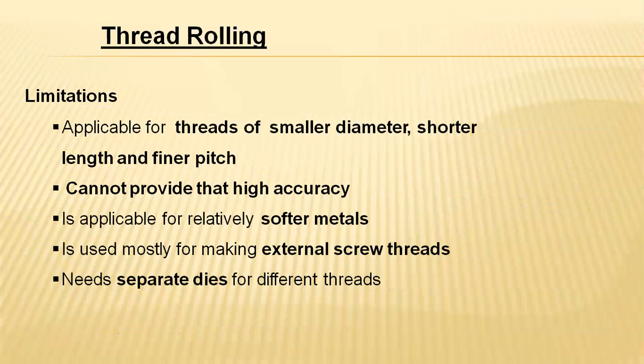Coming to the limitations, the disadvantages of the thread rolling process: it is applicable for threads of smaller diameters, shorter lengths, and having finer pitch levels.